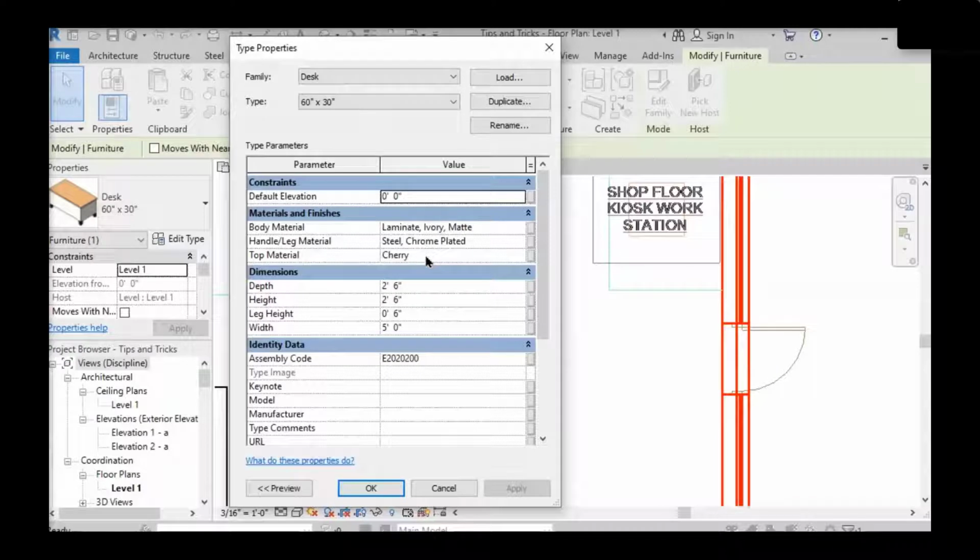But a faster way is you can actually just click in here, do Control C for copy, then select the field that you want to copy it to, then Control V for paste. Go ahead and hit enter so that Revit will recognize that. So now you've successfully copied the material to another part of that family. So I thought that was really kind of neat, and just like never realized that would work, but it does.